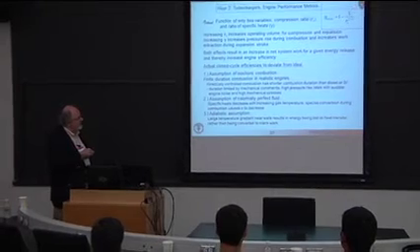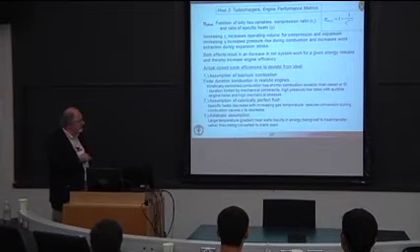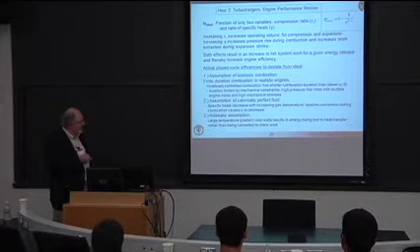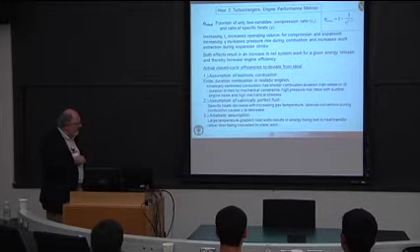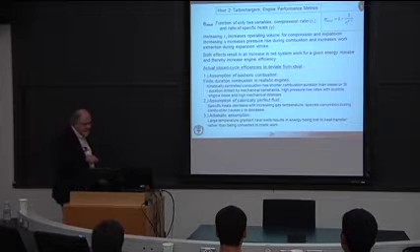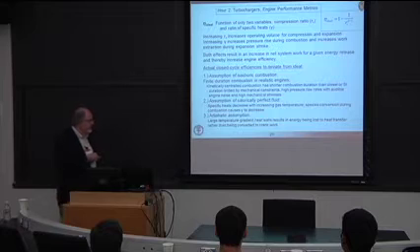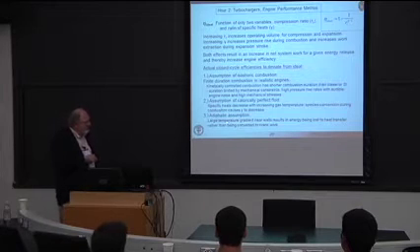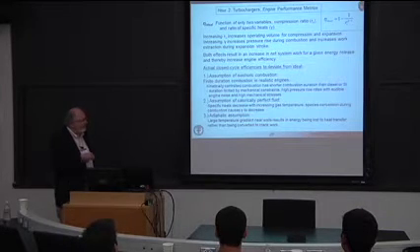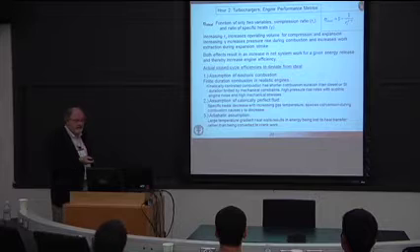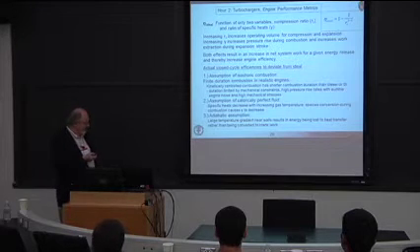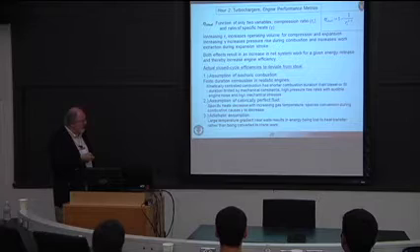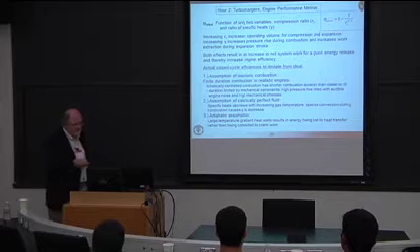So that affects the actual efficiency that you would experience. And then finally, the adiabatic assumption, which goes along with the isentropic assumption. In reality, you have very large temperature gradients near the wall because combustion is taking place in the combustion chamber. That leads to heat transfer. And so that, again, detracts from this ideal estimate.